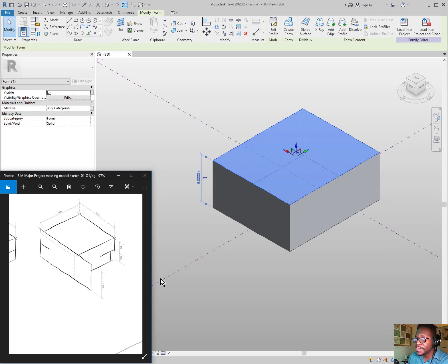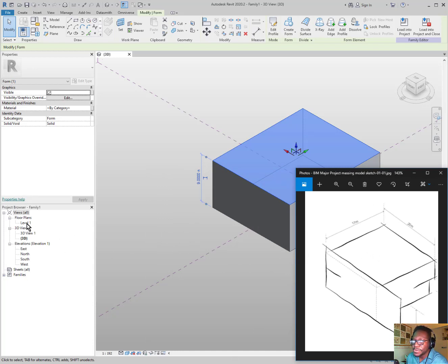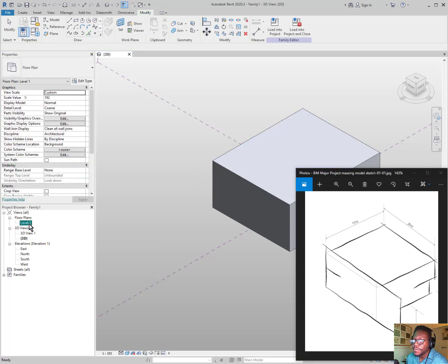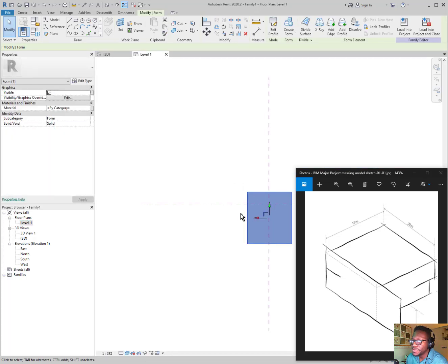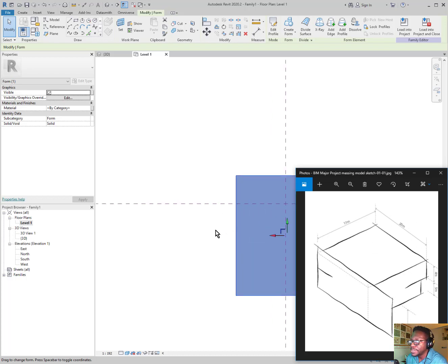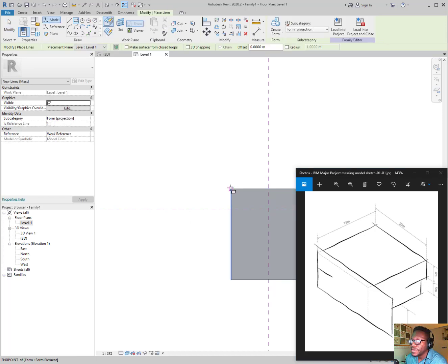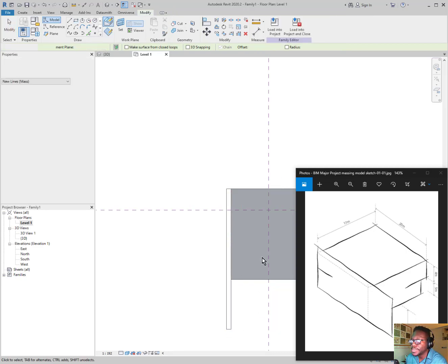And we can see that in our exploration sketch here, we placed a wall here that seems to extend this length. So we're going to do the same there, and there are different ways that we could do that. Now we could just do it in 3D again, but I want us to explore a bit more. So we're going to go to the level 1, which is our plan view here, and you can see that this wall is parallel to the 20 meter area. So we're just going to draw a model of that wall. So I'm just going to use the rectangle tool and just draw a rectangle like that, and that's our wall.